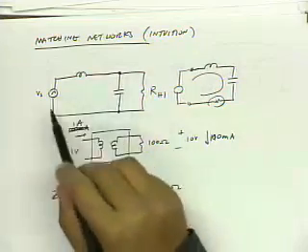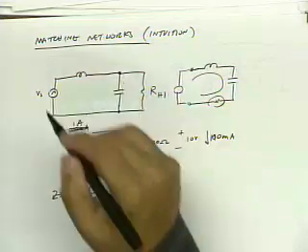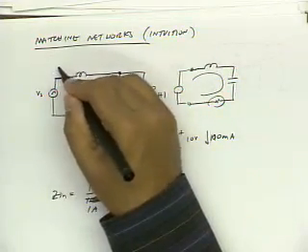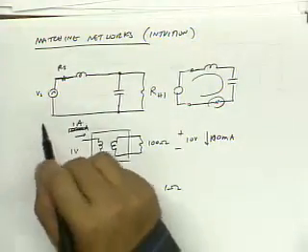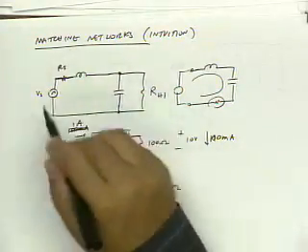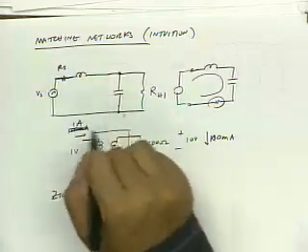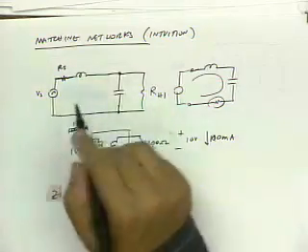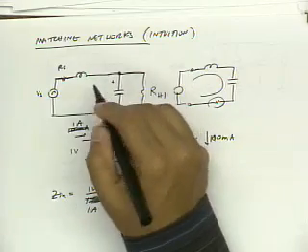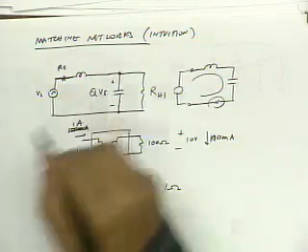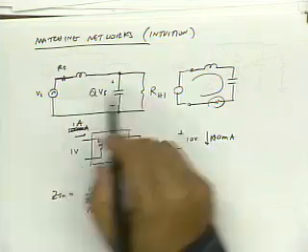So in this circuit, what happens is, if I drive this with some source resistance RS, then at resonance, if this is designed to be a matched circuit, the current is just Vs over 2Rs, right? But the voltage across the reactances is Q times Vs, right?